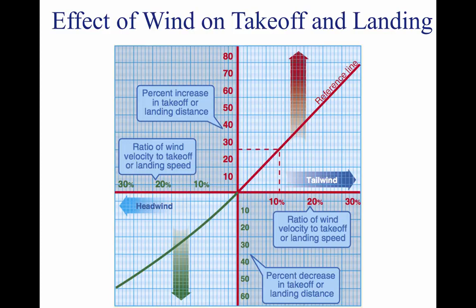Any attempt to take off below the recommended speed means that the aircraft could stall, be difficult to control, or have a very low initial rate of climb. In some cases, an excessive angle of attack may not allow the aircraft to climb out of ground effect. On the other hand, an excessive airspeed at takeoff may improve the initial rate of climb and feel of the aircraft, but it will produce an undesirable increase in takeoff distance.